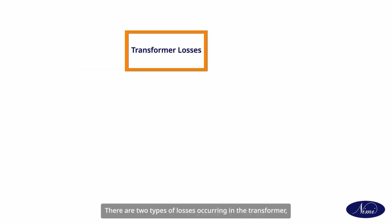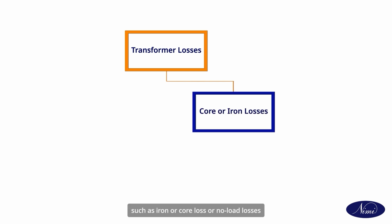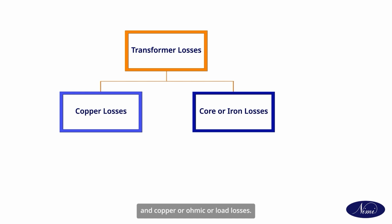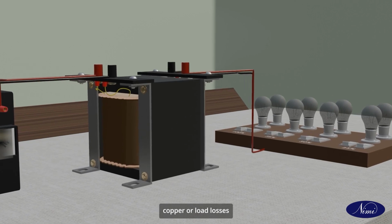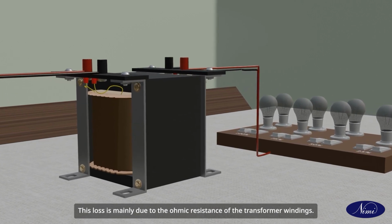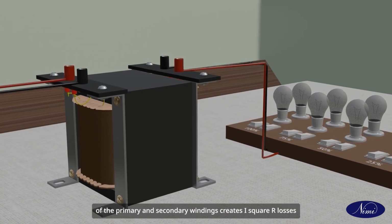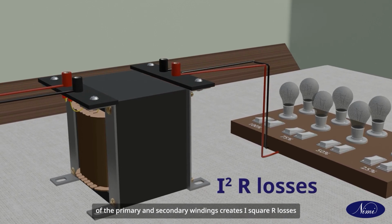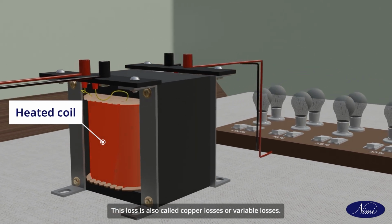There are two types of losses occurring in the transformer: iron or core loss, also called no load losses, and copper or ohmic or load loss. The no load losses consist of two components, that is hysteresis and eddy current. Copper or load losses are mainly due to the ohmic resistance of the transformer windings. The load current through the resistances of the primary and secondary windings creates I squared R losses that heat up the copper wires and cause voltage drops. This loss is called copper losses or variable losses.